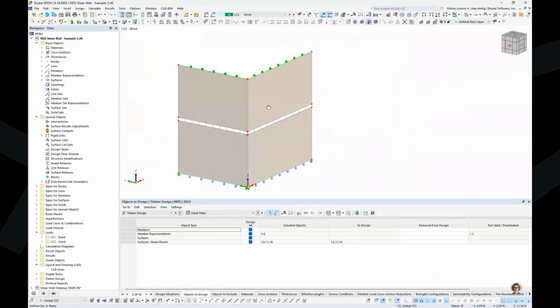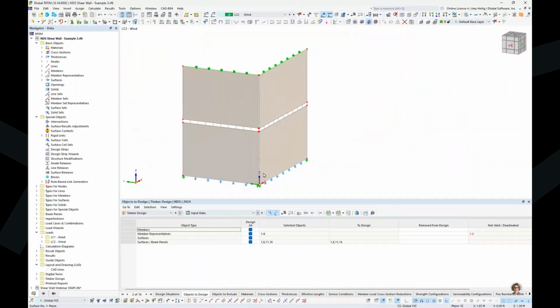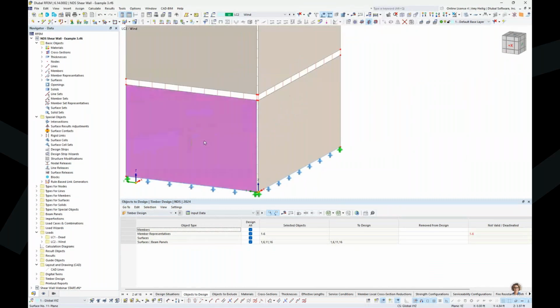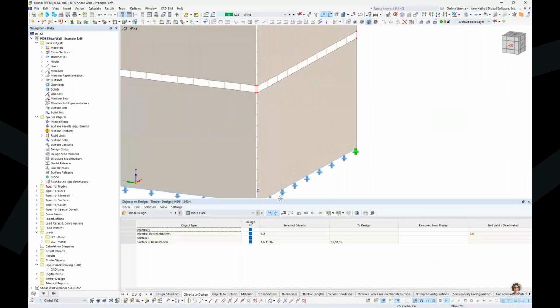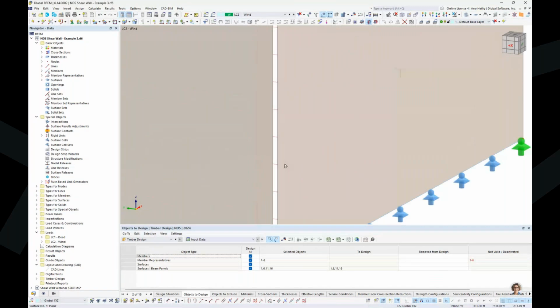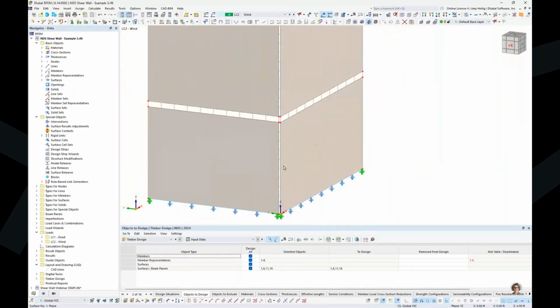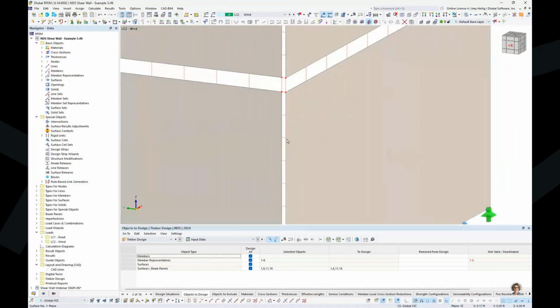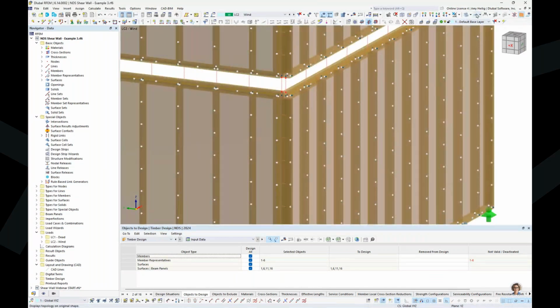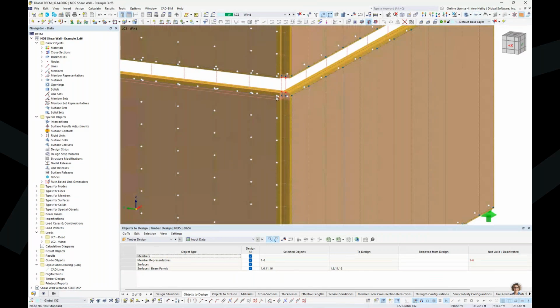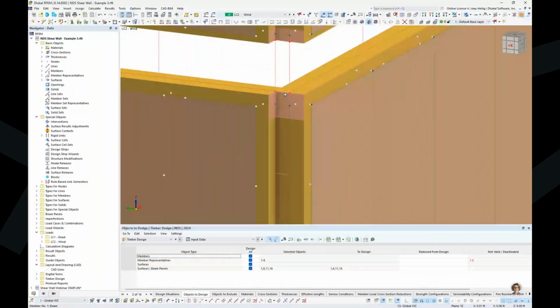The other thing that I really wanted to mention too is when we're talking about wall elements framing in 90 degrees to each other, such as this scenario, it is suggested in the current state that you do model a slight gap here to account for just a small distance. Again, connecting this with the rigid links. The reason why is because when I turn this into the detailed view, and maybe I'll even go to the rendered view here, solid, everything lines up perfectly.